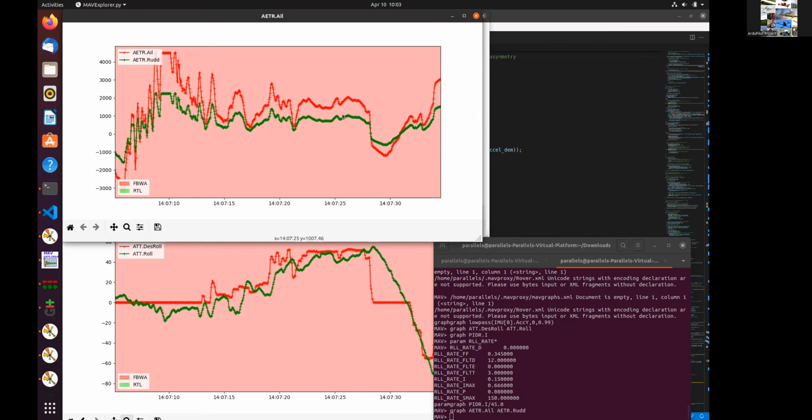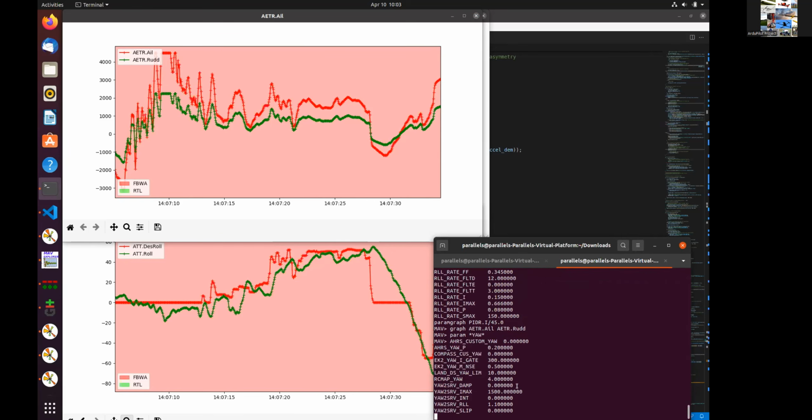One thing is we don't turn on the yaw damper by default. No, I don't think the yaw damper would have helped unless they turned it on. They would have had to have had the yaw damper on and tuned, or at least on, and they would have had to have had the side slip controller gain turned on. Yeah. We could think about whether we're going to enable those by default. If we could make those automatically tune themselves, then actually have the side slip controller enabled.